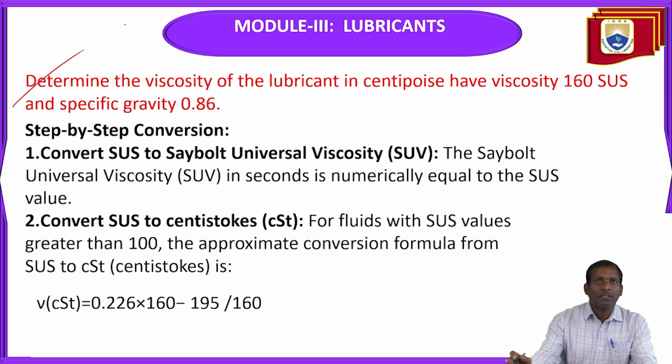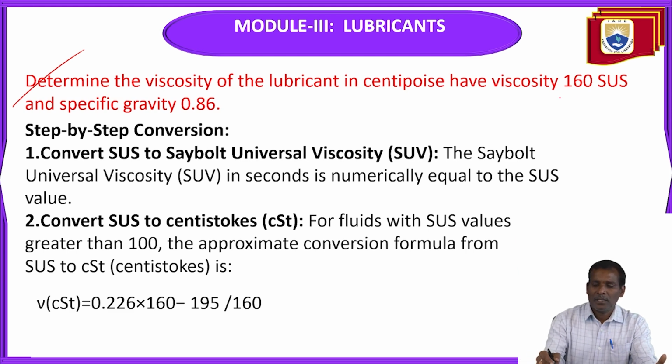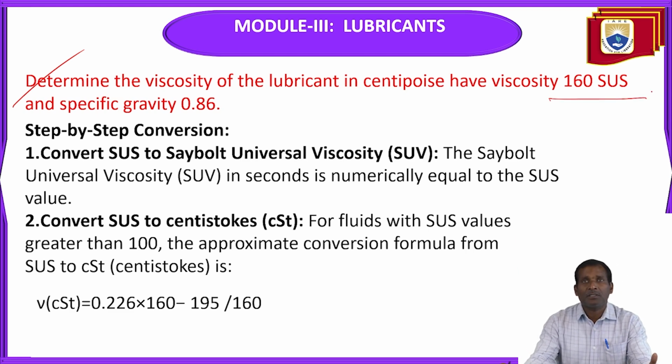The problem is: determine the viscosity of the lubricant in centipoise, having viscosity 160 SUS, that is Saybolt Universal Seconds, and specific gravity 0.86.